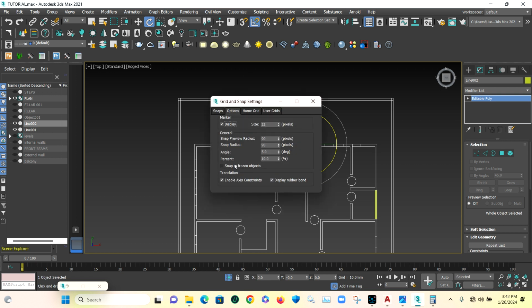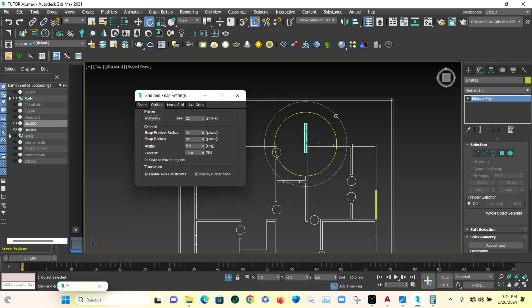So you edit. You see that this is the angle now. It is on 5. Now that it's on 5, if I'm rotating, it will rotate at 5 degrees until I get whatever I want. But now I want it to just rotate at 90 degrees. I want it to be 90, 180, and I am done. So that I maintain my straight line. If I start going in 5 degrees, I might get to 85 and I wouldn't know. I would think it's 90, then I'll make a mistake. So I just go straight. Make sure that whatever I have is where I want it. This angle is the only thing you're changing, please.